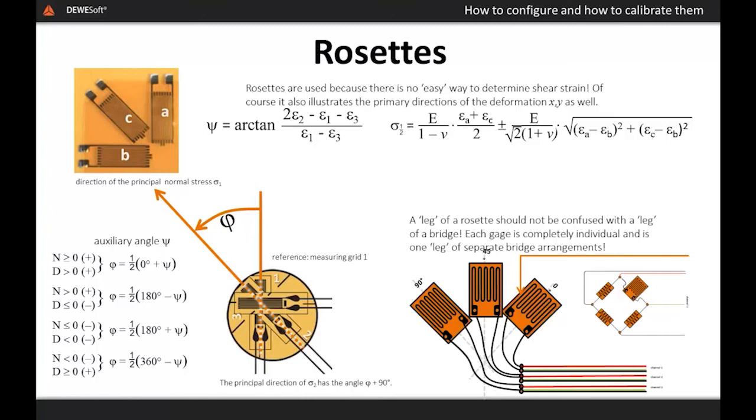In some cases, if the system is powerful enough, it can do this in real time as you collect your data. In these cases, I would recommend that you still preserve your original data, as anomalies can cause some confusion. Some systems record the original data as a matter of course anyway. Young's modulus is required if you're using rosettes, as results are typically resolved to stresses as well. Again, the math looks relatively heavy duty and you may never really care much for what is going on, but as with many of the formulas associated with strain gauges, it's worth at least seeing it.